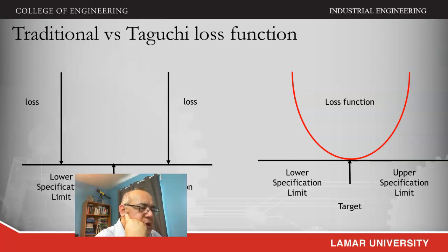And it used to be that for a product to be, let's concentrate on the left-hand side of this diagram, for a product to be within quality, it was enough that it was between the specifications. And if it was between specifications, then the product will be okay regardless of where it is. You have a target in the dimensions, for instance, and if you are fluctuating around the dimension within the specifications, then you're fine. Only you have a loss if you go beyond the limits for those specifications.